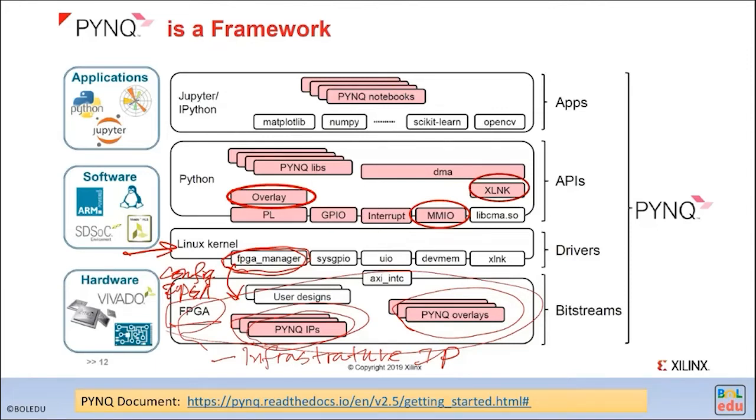The FPGA we use is SRAM based. There are several types of FPGA. Some are anti-fuse, some use flash memory, and neither of them can do real-time programming.